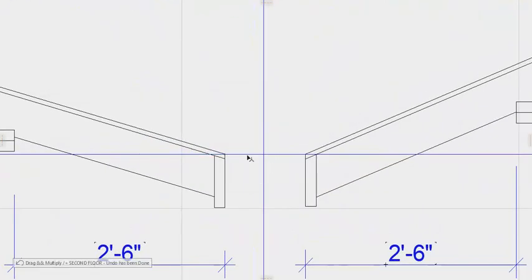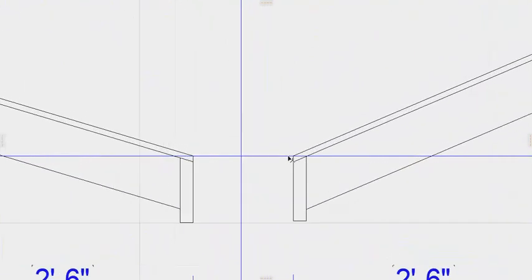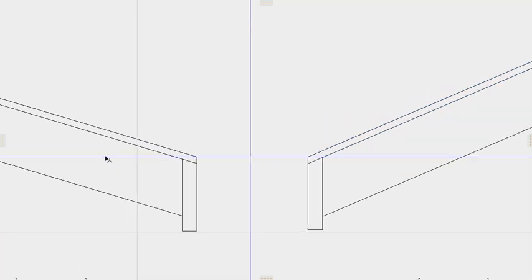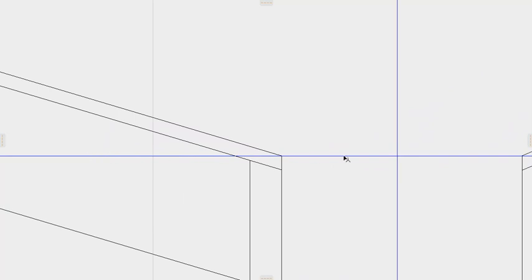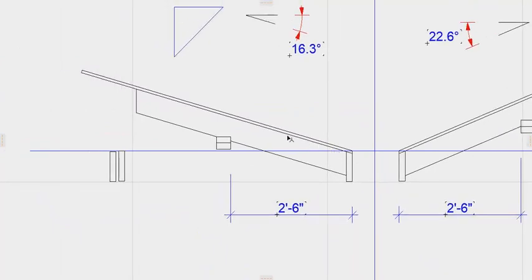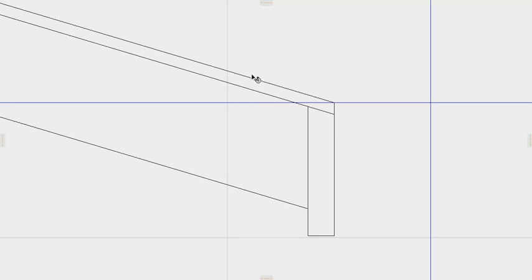And what you want to do is have a line, one of your perpendicular lines here, and you're going to use it to line up the top of your plywood on the other side when you do the other roof. So you want to have a line that you're working on and you want to be on the same line for the other one. So you've established the top of that line, and then you would offset that line 5/8. So you make another line parallel to it, 5/8 inch across, or whatever your plywood is. Just make it the same as your sheathing.